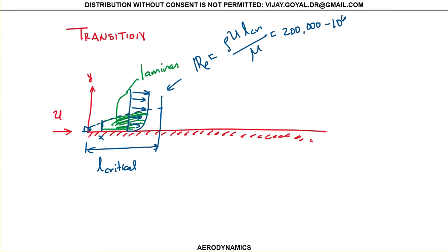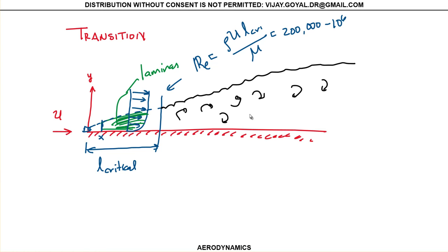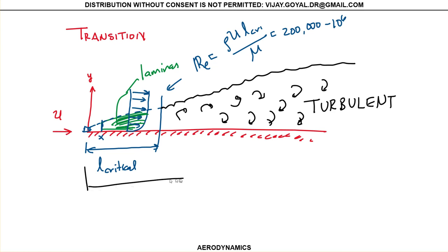And beyond that region, this is what's going to start to happen to your flow. So now you're going to have lots of wakes. You're going to have vortices that generate in here, and these vortices are called wakes. Because of these wakes, this whole region becomes turbulent. And you can immediately see that if something is very turbulent, it's not necessarily a good thing. We don't like that. At an arbitrary distance over here, I can call this letter L. Then your Reynolds number anywhere here would be rho times U times L divided by mu. That's how we define that.